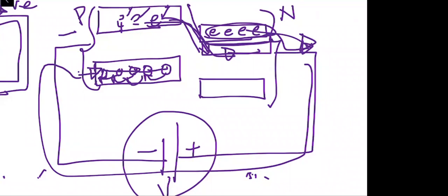So the same kind of impact might occur if the voltage is increased so much in the reverse direction. If that happens, and proper care is not taken, this can actually damage the diode permanently. Some diodes are constructed to cater to the avalanche, and one diode which actually works in the reverse breakdown region is called the zener diode.